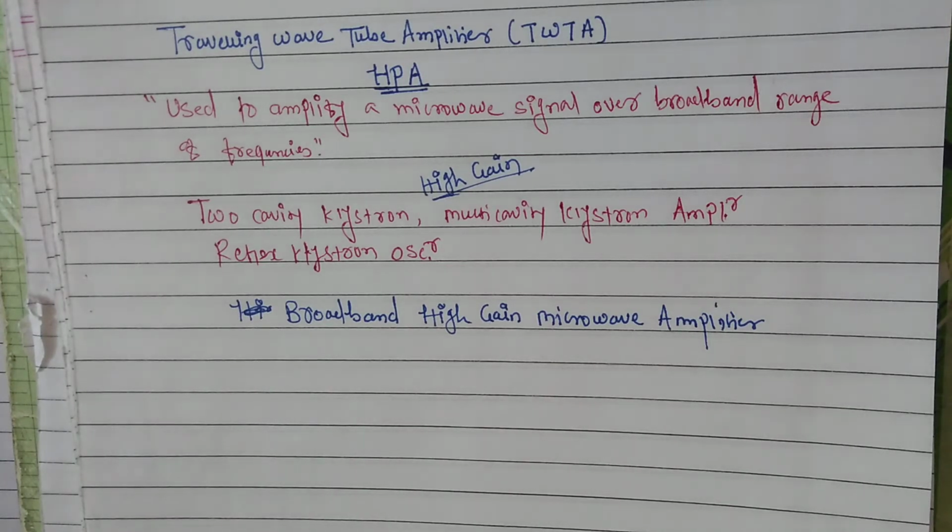If you remember, we also discussed the gain bandwidth product limitation. As the operating frequency is increased for any resonant circuit, the reactive elements such as inductance and capacitance must be decreased in order to maintain resonance at the operating frequency.